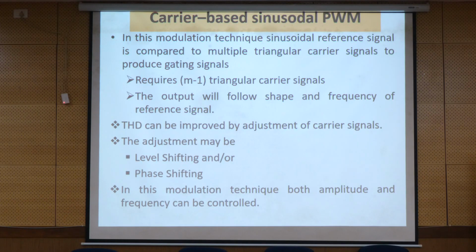But when it comes to the multi-level inverter, you are going to make use of a number of carrier signals and only one reference signal. There are a series of cascaded inverter modules. How are we going to give the switching pulse, so that the first converter operates and then the second converter operates? How are we going to make the pattern?